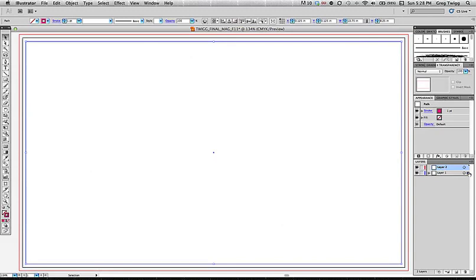There's that little square on the far right, which means that anything you have inside this layer that's selected will be represented by the square. If you want to do anything with it, you could just simply move it into a new layer. So as I drag that little square up, I don't have to open up my layer at all. All I have to do is just select that square and push it up into the new layer.